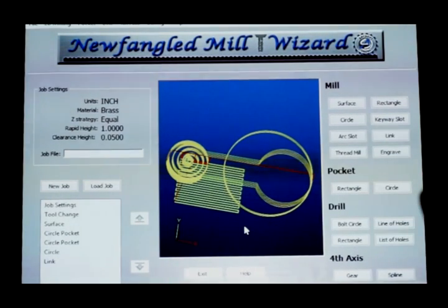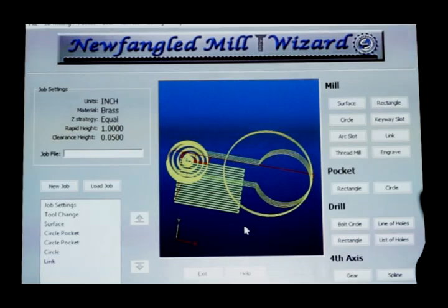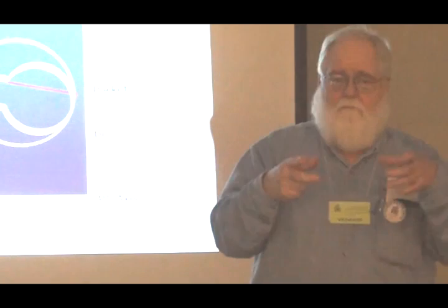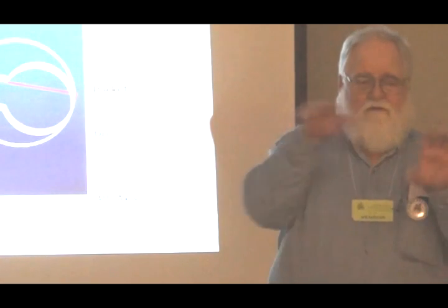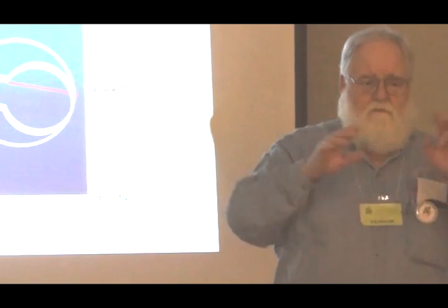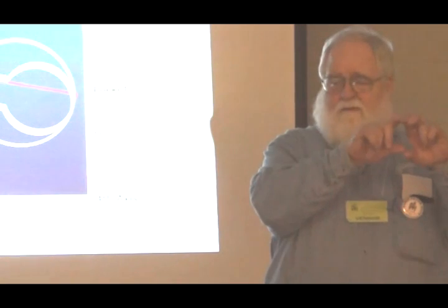Now, I was doing a part like this for the Stuart Turner number 4, right? A situation where I'm making a link. There are two towers that stick up out of the ends of that link, but they're of different heights. And I had a square block of stock to make it on. I put it in the vise, and I first did a finishing cut over everything to establish a 0 and a clean top height of the top cylinder.